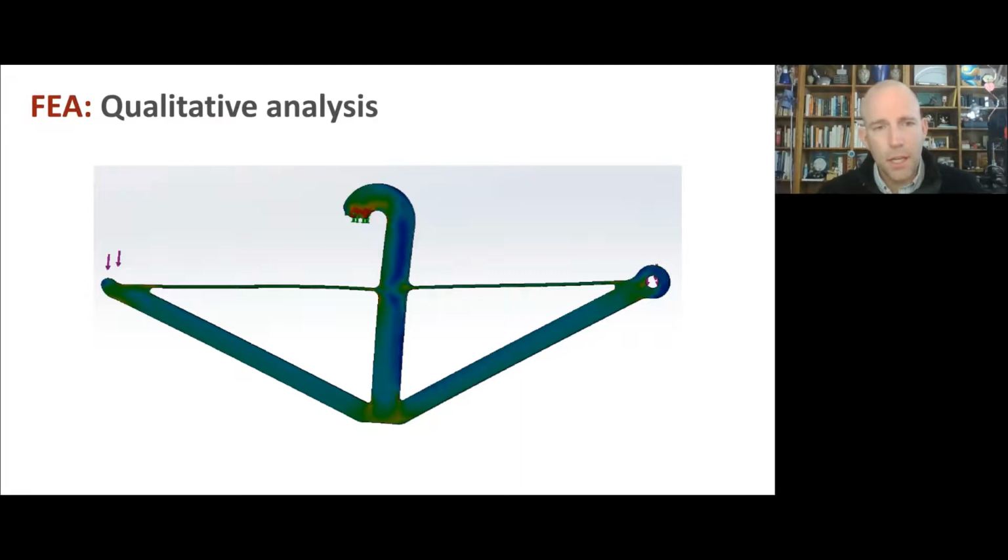In this case, one of the important decisions we had to make setting this up was how to run a quick finite element analysis. We can't just apply forces at all three places, because then the slightest imprecision or numerical error will send things shooting off to infinity. SolidWorks won't run the analysis. So we have to do some kind of fixturing. In this case, I've fixed this face and then carefully calculated the forces that need to be applied here and here to achieve static equilibrium.